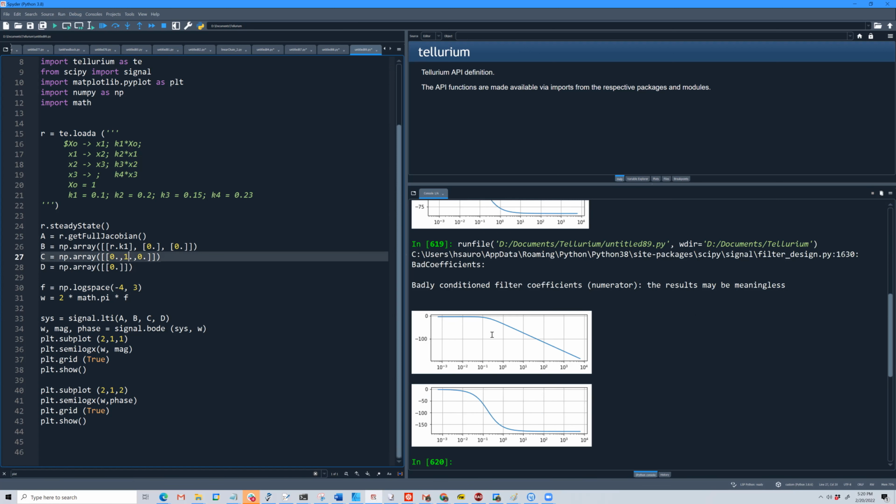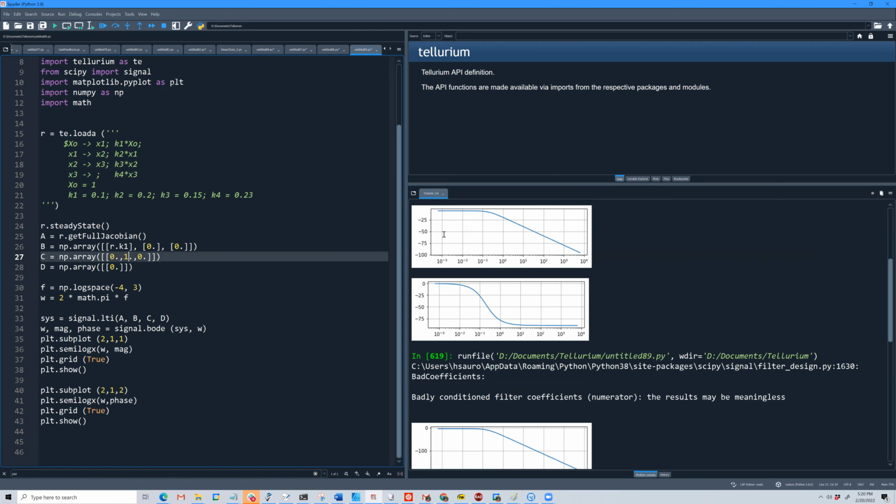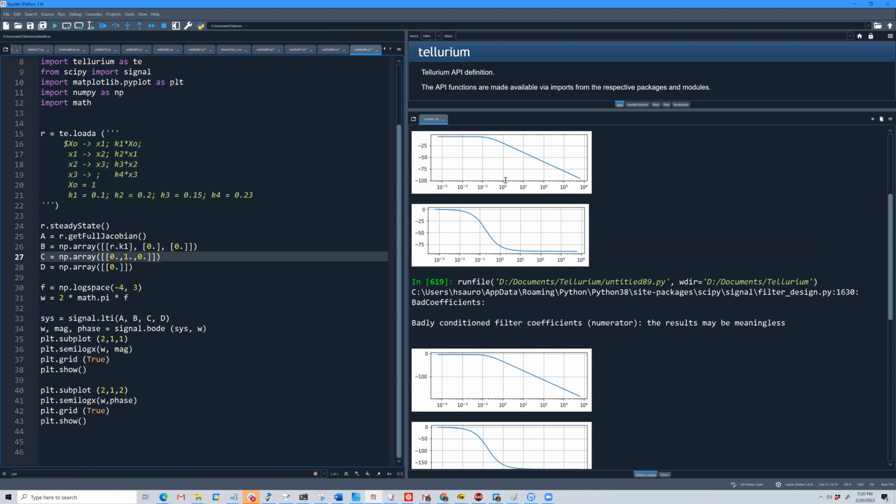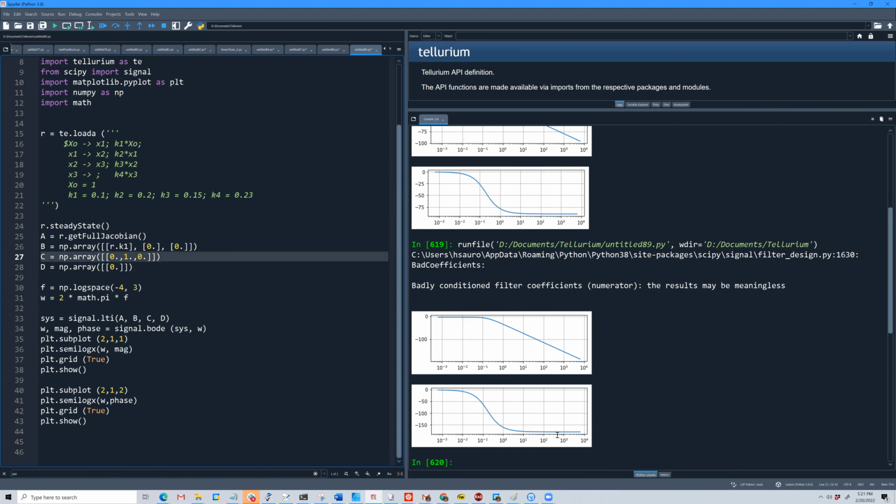And here we have again. Notice the amplitude falls off more for x2. Perhaps if I move this up a bit, you can see that it falls off and goes down quicker. At least the fall off is quicker. What's more interesting for us is that the phase shift goes down to minus 180 degrees. In fact, it's shifted by another 90 degrees.